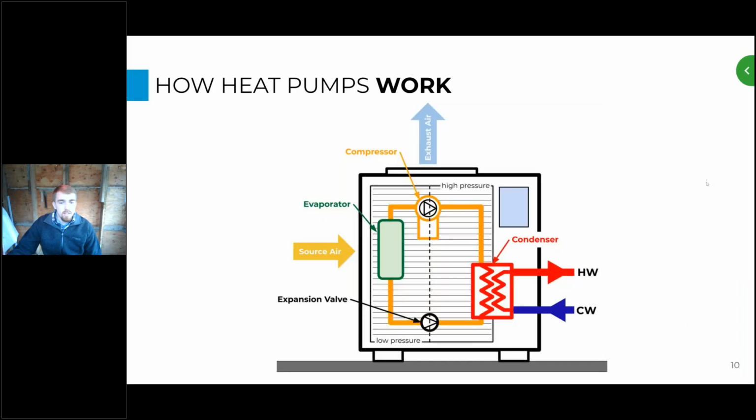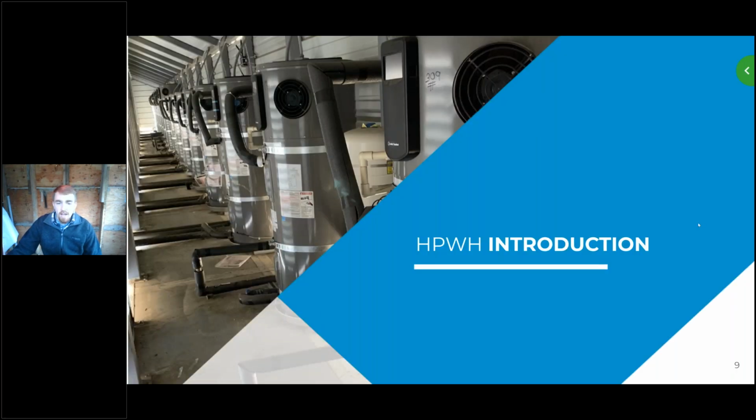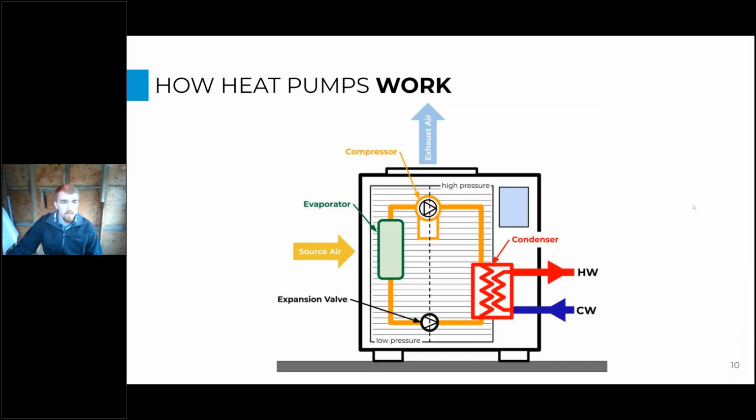So I'm going to introduce how heat pump water heaters work before we talk about how they're implemented in the overall system. When we think about heat pump water heaters, as I mentioned before, we're not talking about creating heat with electricity as we do with electric resistance, or creating heat with gas by burning a flame. We're actually just moving heat using the refrigeration cycle.